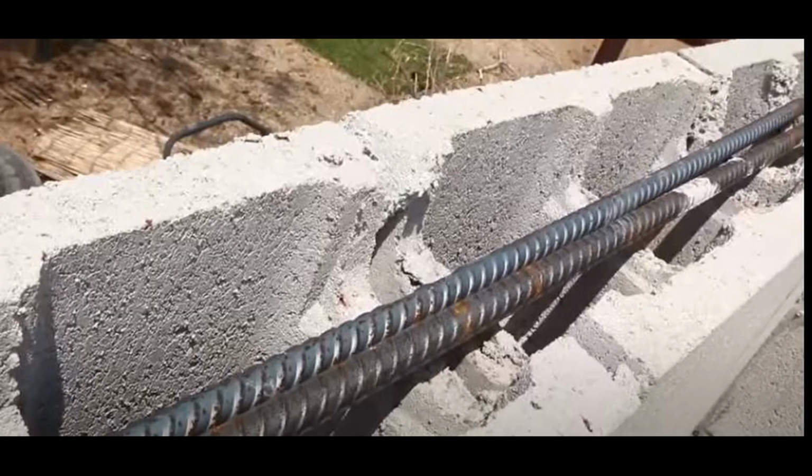The fourth and last, bond beam. The bond beam has no role in providing sufficient strength. Firstly, it has been installed on the top course only, and secondly, this MCB wall does not take any lateral soil pressure at the top, so it is overkill for construction of this concrete block retaining wall.